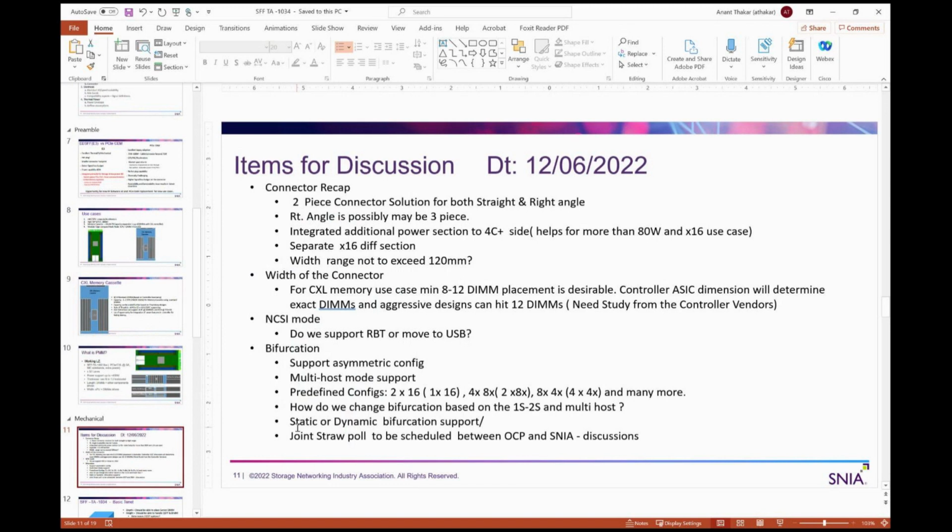I think CMS has to really see how we can do this kind of pre-BIOS environment also. Anand, fundamentally, this presetting of the multi-host memory device needs to happen before the enumeration takes place. Of course, we need to discuss how to make this secure from the root of trust, making sure the root of trust confirms this request. Yeah, we'll need to discuss it.